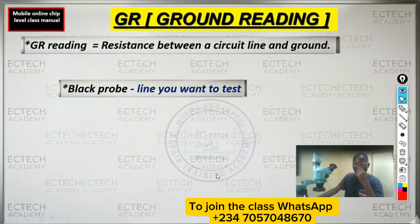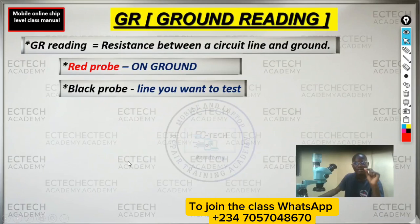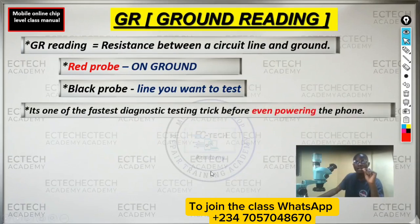In order to carry out the GR reading on a multimeter, you have to place the black probe on the line you want to test and the red probe on the ground. That's the way of placing your probe if you want to get the actual result of a GR reading. You remember in our code testing class, this is also called reverse reading. It is one of the fastest diagnostic testing tricks before even powering the phone. Before you insert any power source like a battery or charger into the phone, this is one of the fastest methods of testing to find a fault.